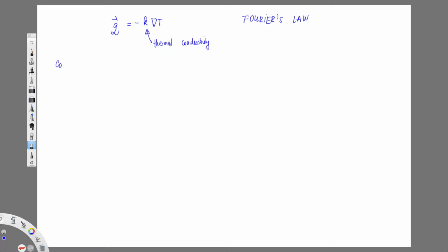So I'm going to call this the convective energy flux vector. And that stuff that flows in basically has a direction of velocity, and that's also the rate at which it flows in. But what flows in? Energy. How do we quantify energy? One part is the kinetic energy, and the other part we refer to simply as internal energy.